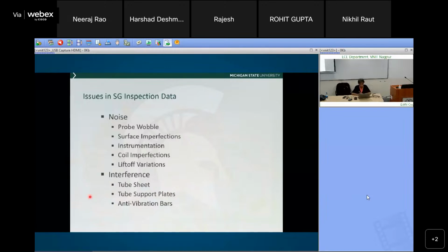Industry has not come to us with that problem. Obviously these are pretty rugged, and there are no moving parts that can break. The only thing that is delicate is the array of Hall sensors that they use. Sometimes you'll find dead channels, when one of the Hall sensors in the whole array can die, and you have a black line over there. So you know clearly that there is something wrong and we can replace it.